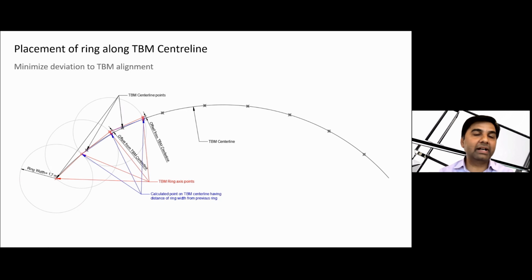We have already tested a few of the tools. The Civil 3D toolkit is already available in Dynamo for Civil 3D. It has a few nodes. You need a corridor first, and then you can put in some parameters, decide which ring, and then you can make all these rings and make the tunnels.